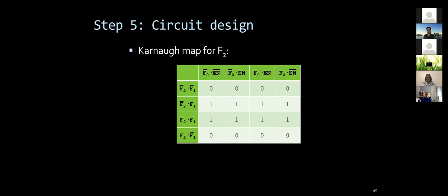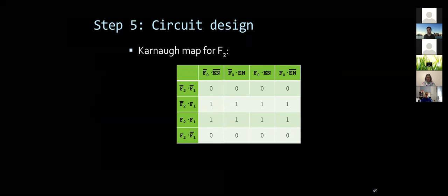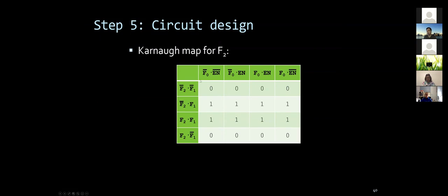So we had F2. We need to compute how F2 is going to operate based on F1. For your own simplicity, remember I said we essentially convert the sequential circuit representation into something very similar to a truth table, right? It has 4 different inputs, and essentially that's like a 2x2 matrix for the K-maps here.